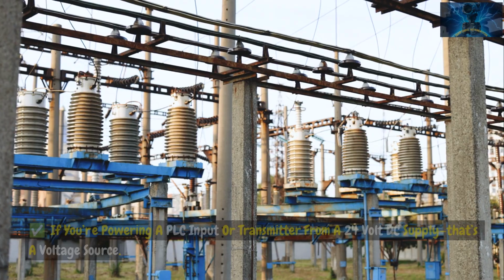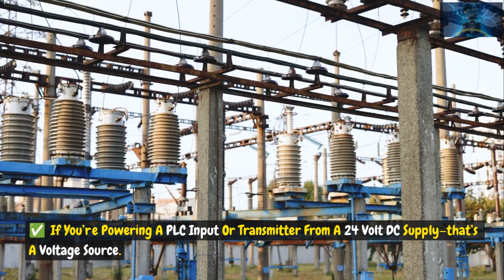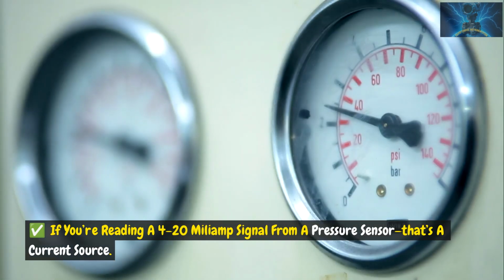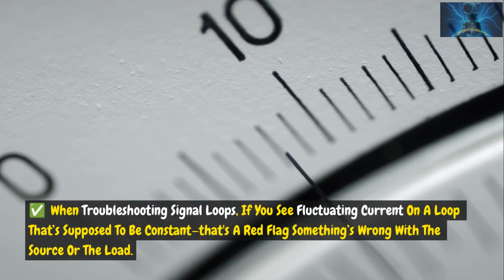Field examples: if you're powering a PLC input or transmitter from a 24-volt DC supply, that's a voltage source. If you're reading a 4-20 milliamp signal from a pressure sensor, that's a current source. When troubleshooting signal loops, if you see fluctuating current on a loop that's supposed to be constant, that's a red flag, something's wrong with the source or the load.